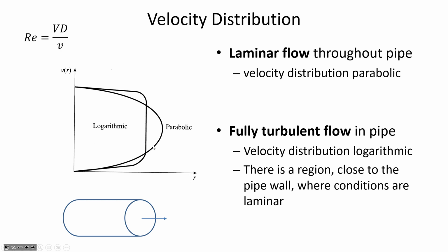There's not as distinct an increase of the velocity at the center of the pipe. It's just once you get away from the edges, then there's some average velocity, and at any given point, the velocity may momentarily be higher or lower than that average, but the main idea is that there is a flat profile that follows a logarithmic function when we have fully turbulent flow.